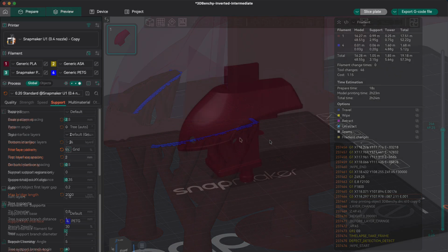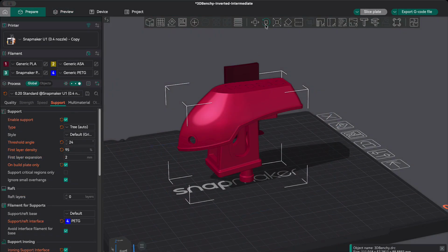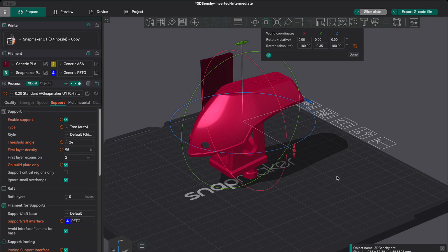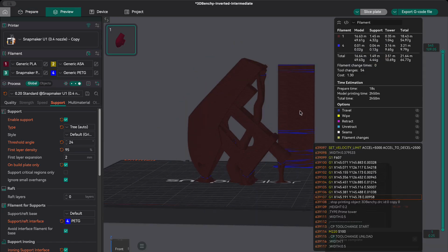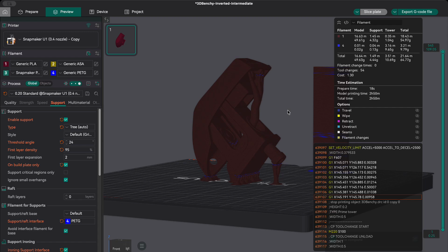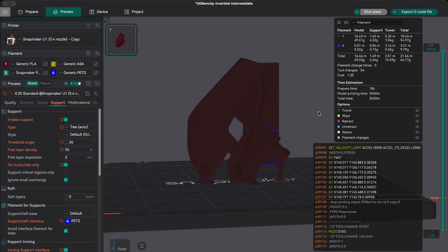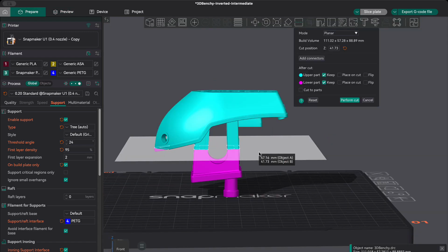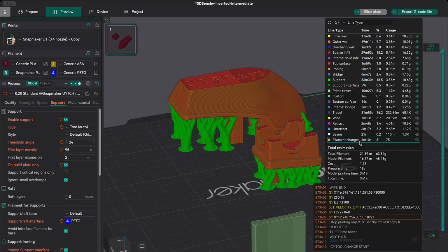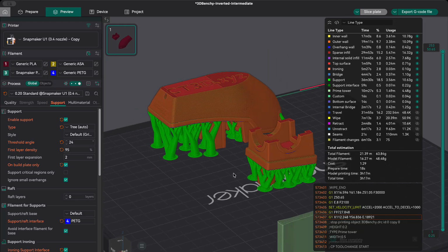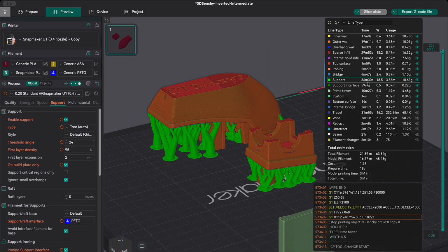through preview. Before tuning individual settings, check the model's orientation. A small rotation can turn a large horizontal overhang into a printable slope, move support marks onto a hidden surface, or replace a difficult support structure with a manageable bridge. For large models, cutting the design into printable sections may produce a better result than building an enormous support structure. Advanced support tuning begins by reducing the problem before trying to solve it with more material.